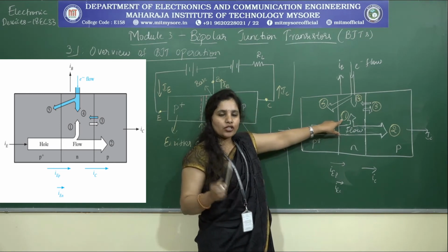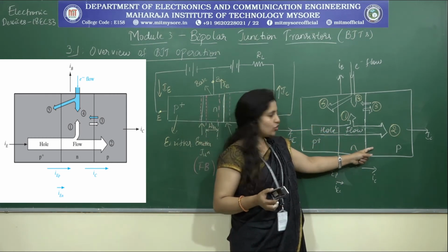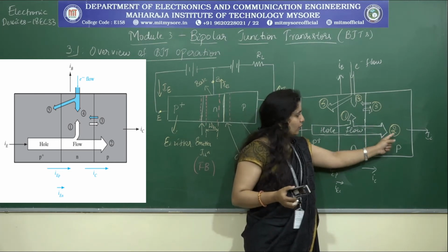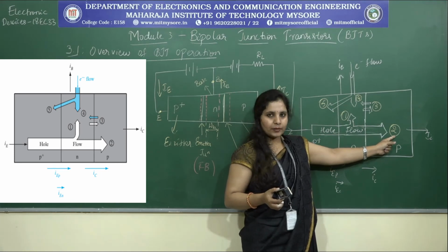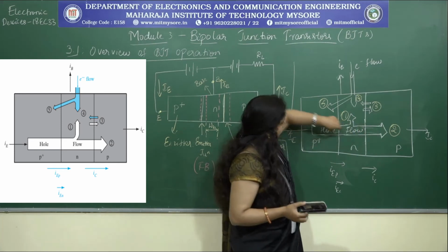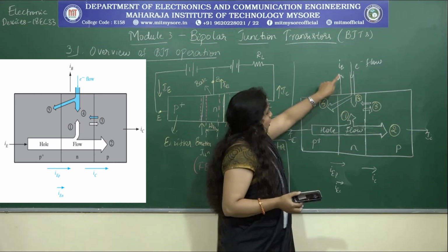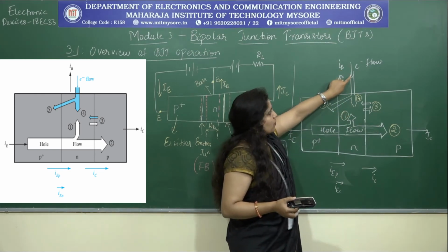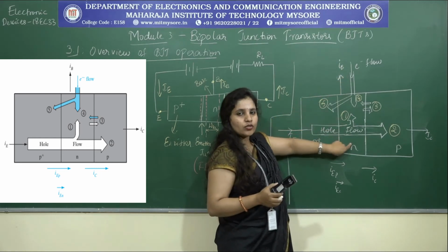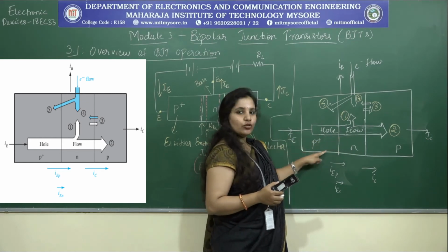Now, after recombination, whatever the left ones that we have will try to cross this reverse biased collector junction and move into the collector region, and that is the current which results in the second component. I hope all of you understood how the arrow size should be till this point and why it is reduced after this point. Done? Now, there is a certain amount of electrons which is provided from the external source, because it has to compensate for the electrons which we have lost in the N material because of the recombination and the moving of holes from N to P plus.